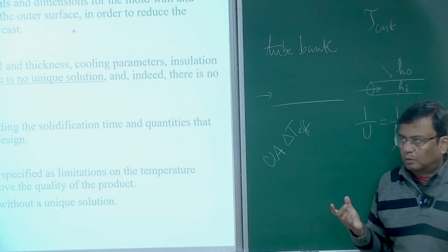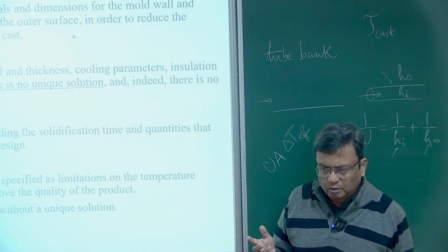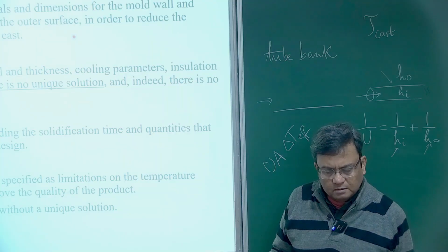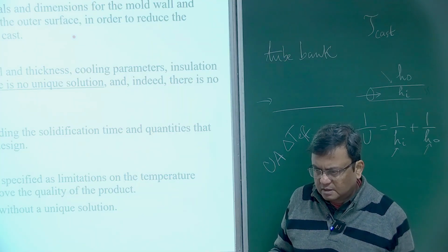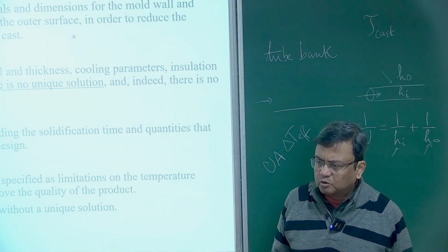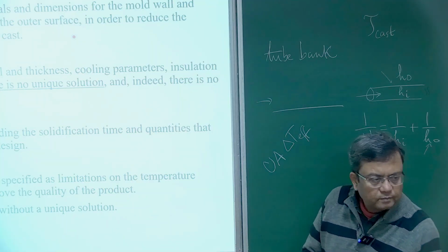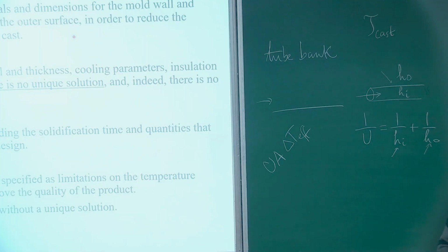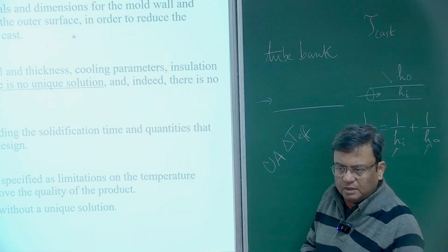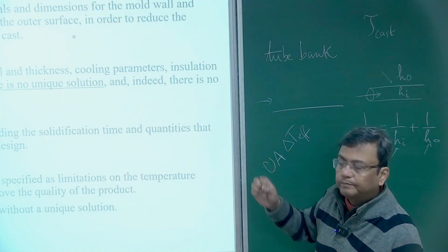You know that the metal property that you're going to get is also going to depend on the casting time, right? Isn't it? And if you give too much time or too short a time, then some things will happen. What will happen? The metallurgical properties, thermal stresses, those things will get affected. Right? So tau cast is an objective, right?